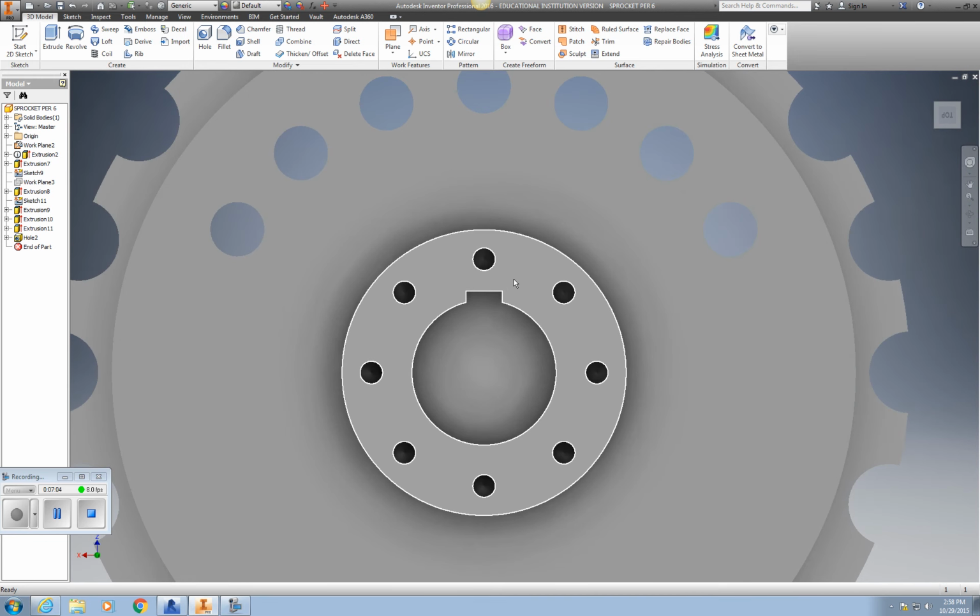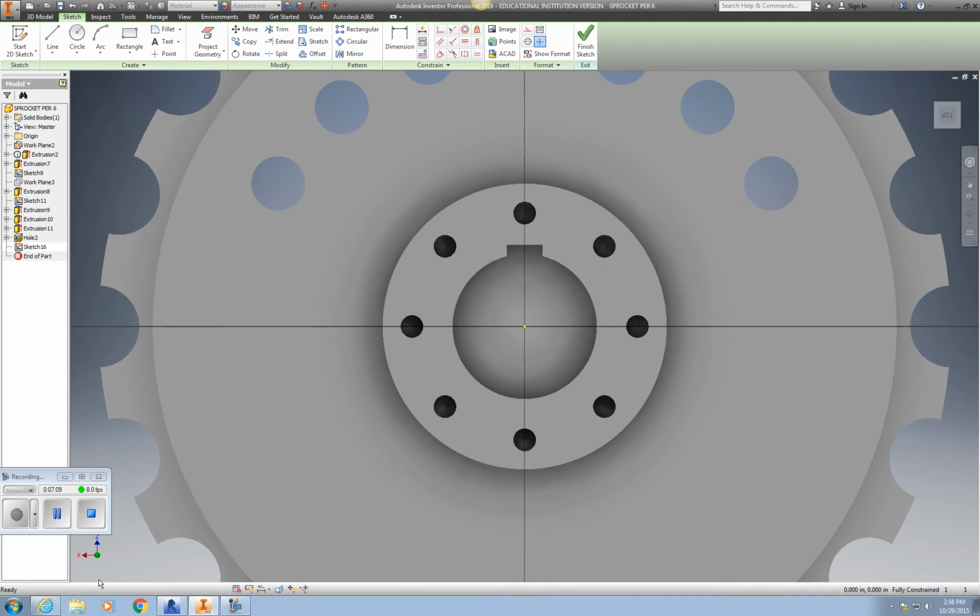same surface. So we're going to have to click on this, create sketch, and we will then place in our 50 diameter. We will now place another 50 diameter circle in the middle. And once again, hit escape, delete the dimension. And we're going to put another circle, which is a little bit larger, at the same quadrant of that 50 diameter. And this will be a diameter of 6.